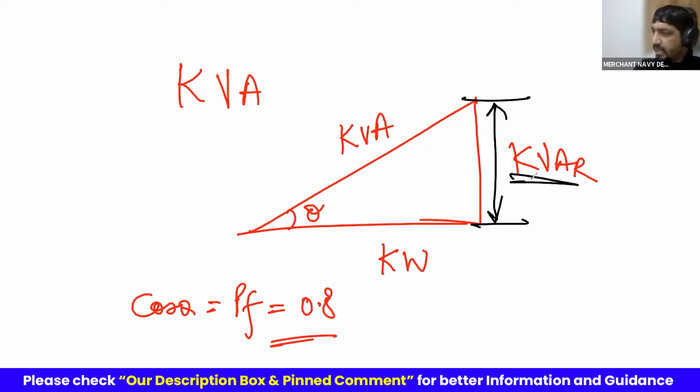This one is shared also between the generators, and they don't share it equally till the voltage is equal. Before paralleling, if the voltage is different, okay. After paralleling, speed and voltage have to show the same on both generators, because they are now already connected. I'm talking about before they are connected.